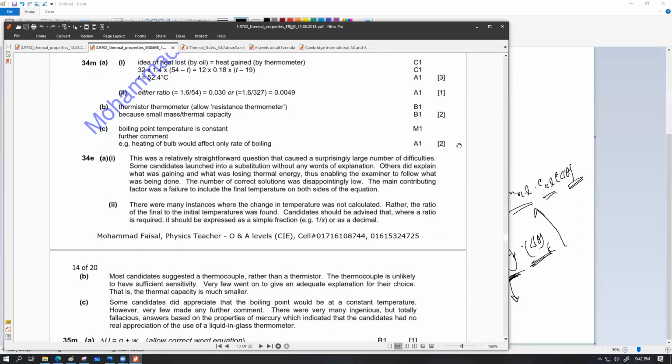Thermistor thermometer works in the same way as the graph that we just came across at the start of the class. With that graph, as the temperature increases, the resistance slowly decreases. So if you know the graph for a thermistor thermometer from previous experience or during the process of calibration, then you can essentially find out the relevant temperature of the object where you are submerging the thermistor.